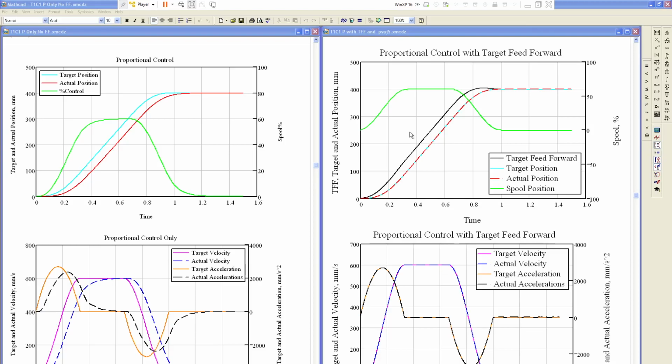And sometimes you have to exaggerate the path a little bit to get the donkey to go exactly where you want it to go. So by having the closed loop part act on the error between this target and the actual position, you can actually get the target and the actual to line up, the real target, which is this cyan line underneath here.